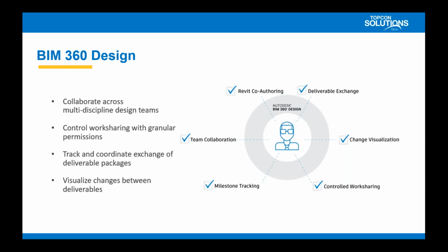Well, there's a pretty awesome workflow there. So think about doing CA type work, and you've got to make notifications to yourself, right? So you can go out in the field, create these issues, assign them to yourself, and then use the Revit plugin for issues for BIM 360, and then actually make the changes that you've assigned yourself to in the field. It's pretty cool. I mean, obviously other people can assign you issues as well, but within Revit itself, in Navisworks too, we can view those issues that you create in BIM 360.